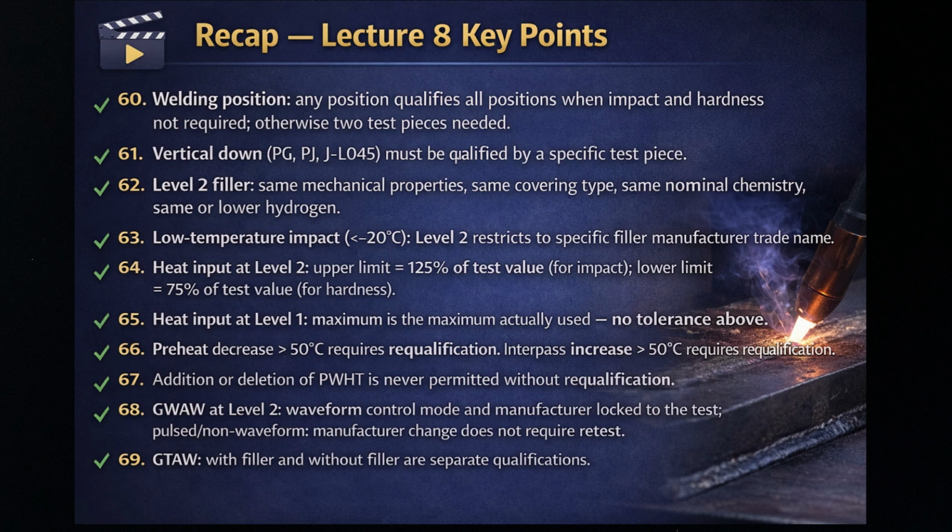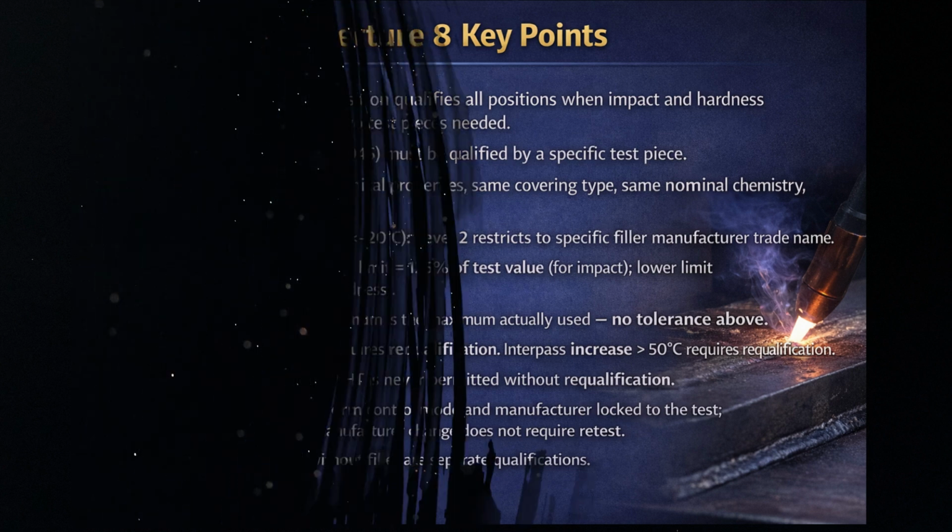GMAW at level 2, waveform control mode and manufacturer locked to the test. Pulsed, non-waveform: manufacturer change does not require retest. 69. GTAW. With filler and without filler are separate qualifications.